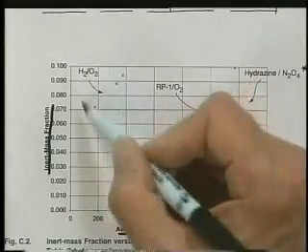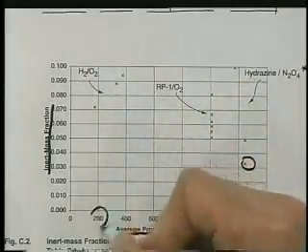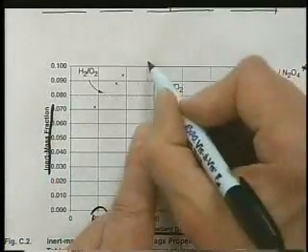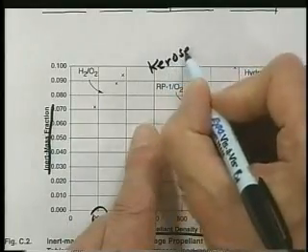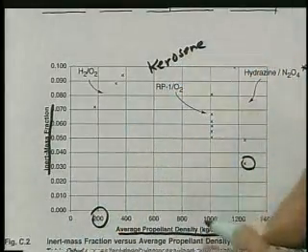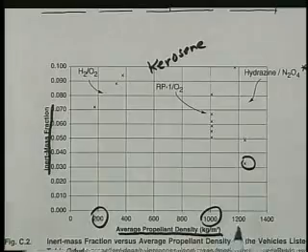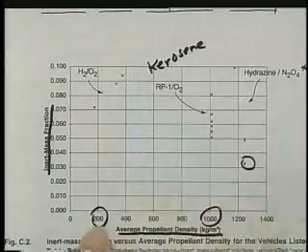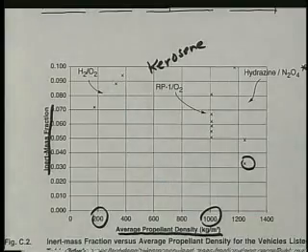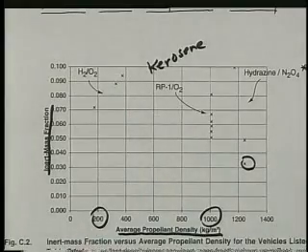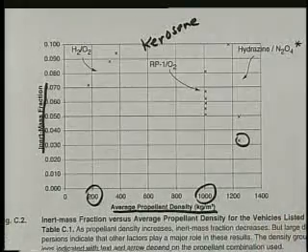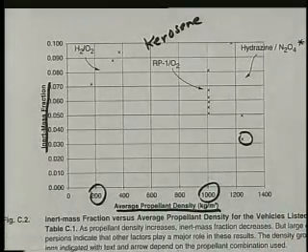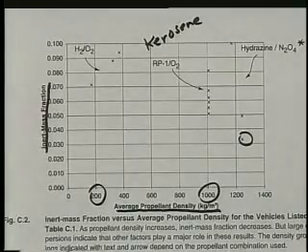We also see that the hydrogen LOX is hovering around 200 here, and the kerosene, RP1, is hovering around 1,000. So that's how we get approximately a 5-to-1 ratio, maybe a little less than 5-to-1 if we go up to here, of course. But just taking roughly the 5-to-1 gives us a dramatic idea of that density ratio and how important it is in the size of your propellant tanks.